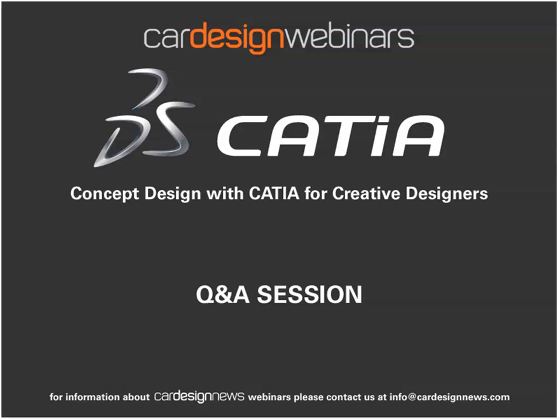And in this knowledge, we added 2 options for the user. First of all, the thickness of the SU, and the second one is the step, the number of SU that we want. And at any time, you can change it. So KnowledgeWare is very interesting to capture the know-how of the company on some repetitive objects. And you can use it with any product. It can be subdivision surfaces, CATIA ISM Class A, G3 continuity surfaces, parametric surfacing or solid modeling.